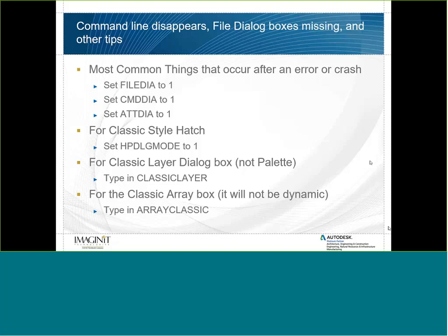And then lastly, for the classic array box, which brings up the old box for the array, it's not dynamic. It will not be dynamic, but you can get back to that behavior and just simply type in ARRAYCLASSIC.